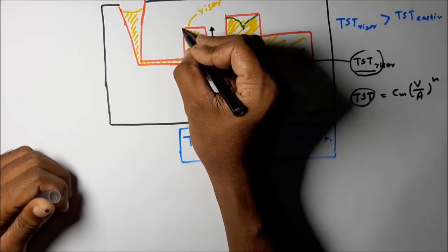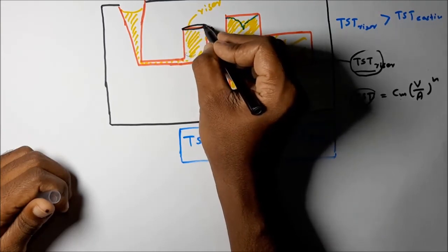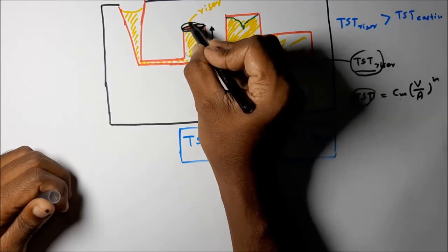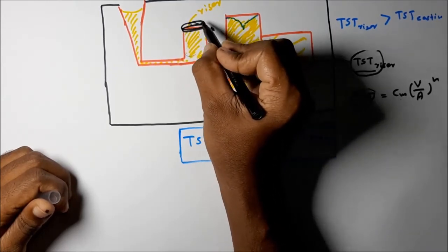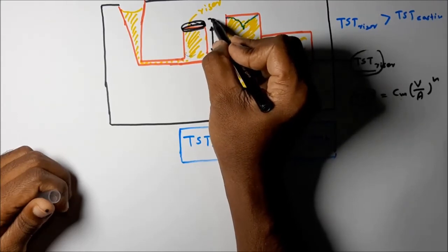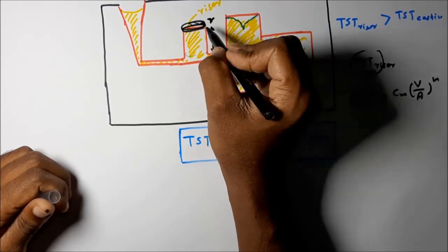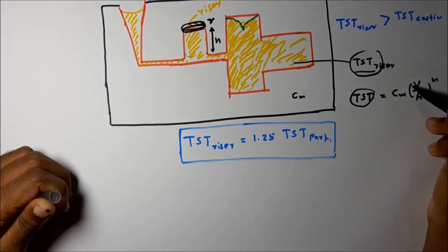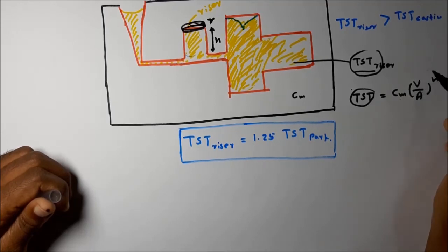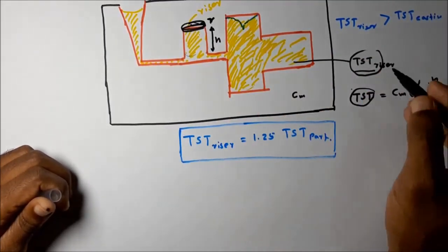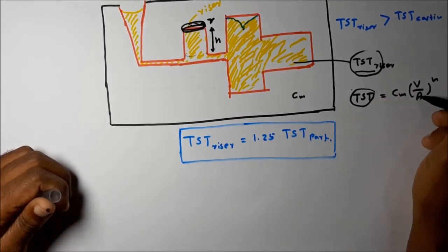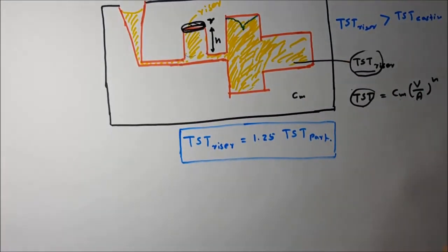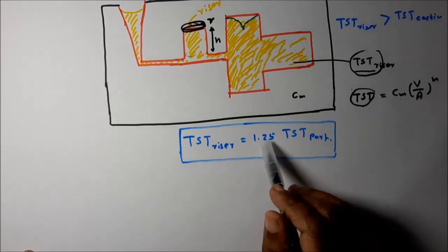Normally we take cylindrical shaped risers. If you fix a certain particular radius for this cylinder, then h is the variable to get this ratio. According to the required solidification time, we have to adjust the dimensions of the riser to get the required solidification time in riser design. Then we can get this relationship.